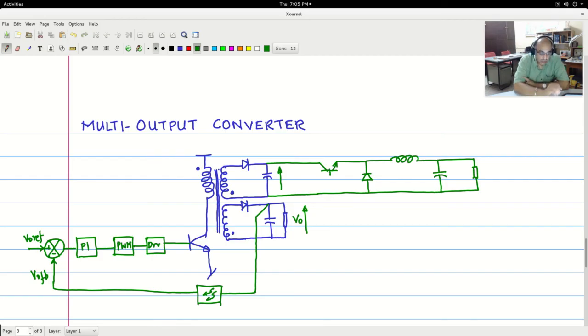Now driving this device is better if you push this device onto the negative rail, that is the return rail, so that you can drive with respect to its base if it is on the return rail. Or if you want to keep it on the upper rail, you can use a PNP transistor or a P device. Now let me just show simple blocks of the circuit so that all would be referred to this particular ground.